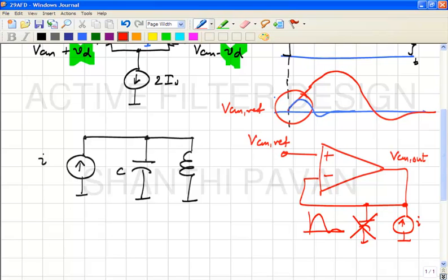So it means therefore that the output impedance of any feedback loop based voltage source must contain an inductive component. You understand? Simply by virtue of delay in the feedback loop or finite bandwidth of the loop.